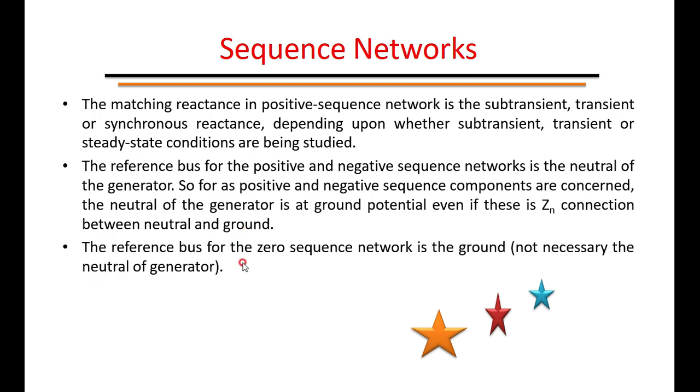The reference bus for the zero sequence network is ground, not necessarily the neutral of the generator. That is, it is a very important statement that the reference bus of the zero sequence network is ground. It is not the neutral of the generator. That is, the neutral is floating in this case because it is an unbalanced condition.